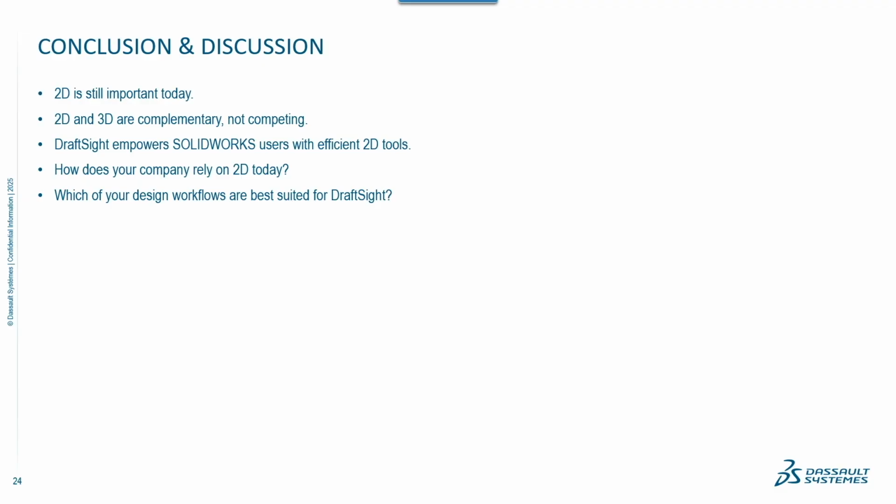Okay, so like I said, my former company, the first thing we did, we were going to SolidWorks. We had a couple SolidWorks users. But the first thing we did is we imported over 200,000 DWG files and managed them in PDM. Now, we didn't use XREFs, but still, it will look at an XREF and handle that reference, and you'll see it in the Contains tab the same way you would with SolidWorks references as well. So, yeah, it really works well. PDM does. And that's either PDM Standard or PDM Professional. Okay?